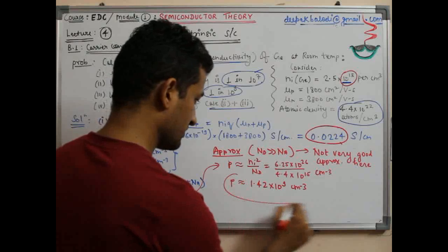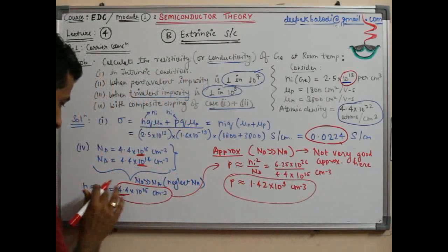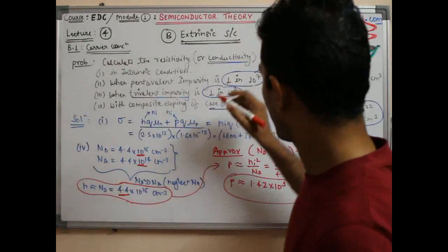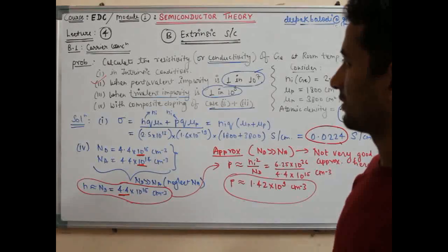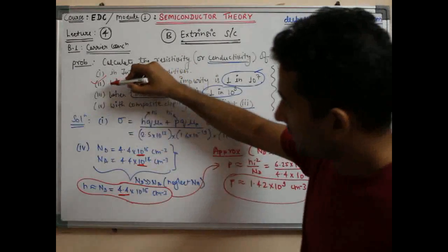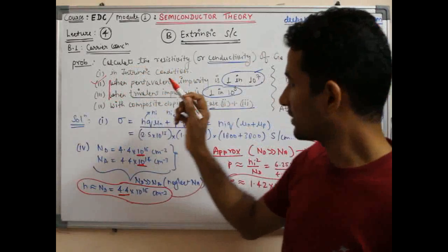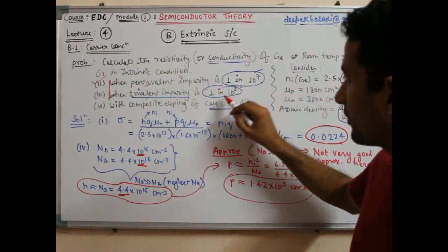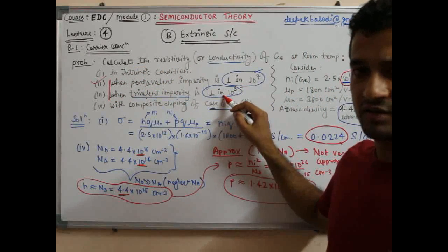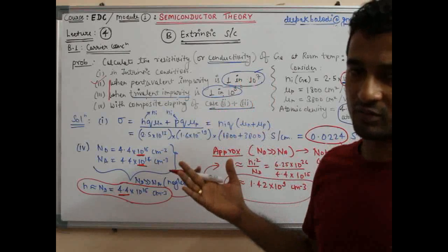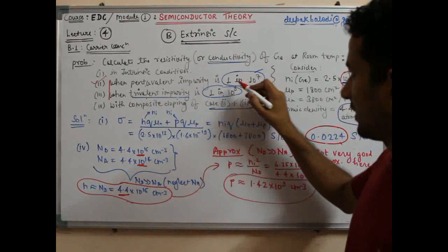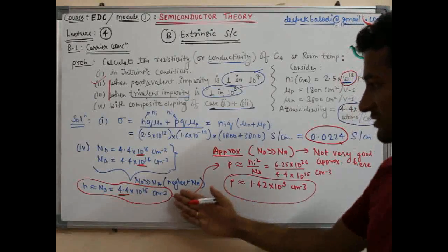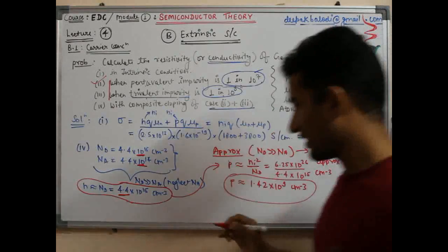So this is P and this is N. Isn't it a similar case to this? When we added these two cases, we still assumed that this is a far greater doping concentration than this, because it is still one order greater. Otherwise you could have gone for the accurate calculation. So if this is greater than this, then ultimately the results will be the same as the second case, so the answer will be the same as in the second case.